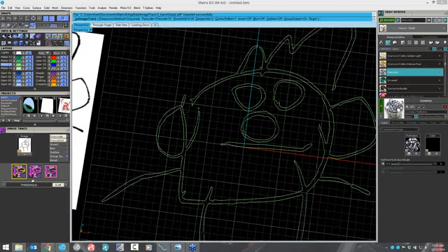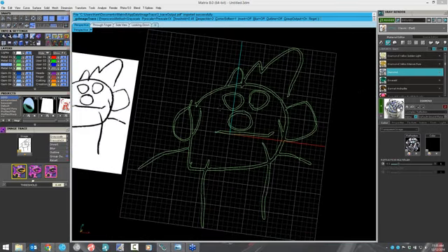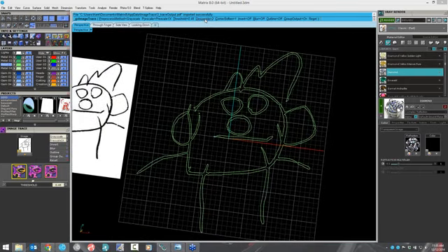You can see we have a couple little dots here. Those we call speckles. And you can certainly come in here, and I'm going to increase the speckle to 4, and it'll get rid of those speckles. We can smooth out the lines by blurring the original artwork. We can do all sorts of stuff.